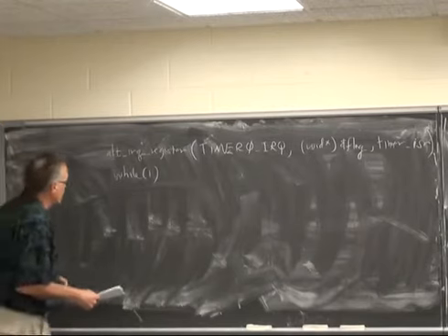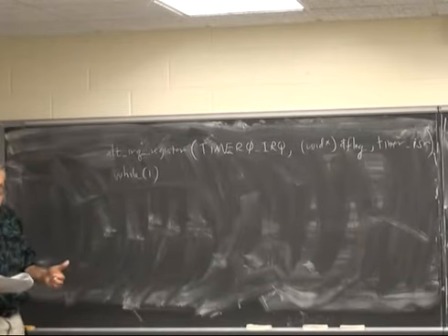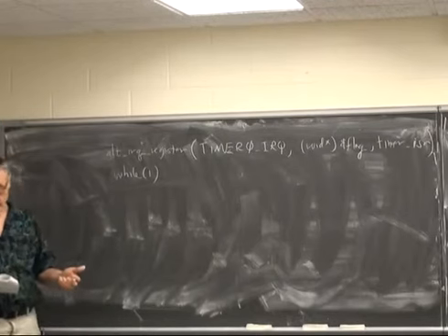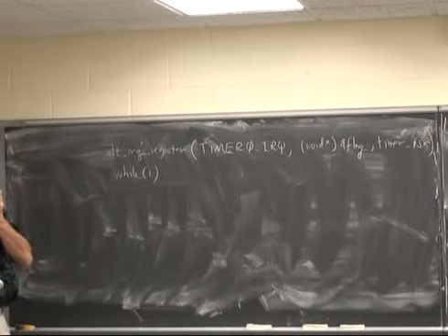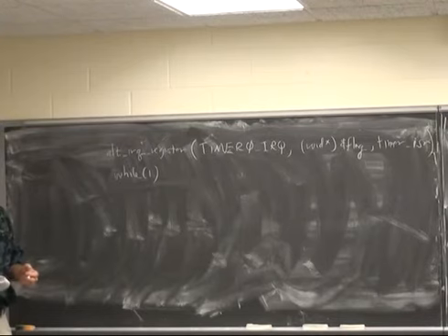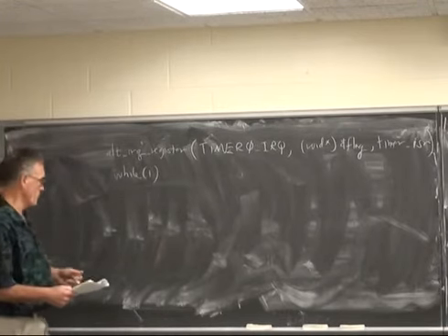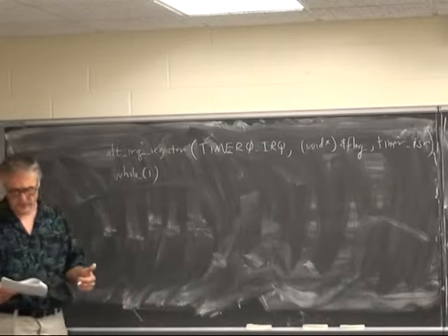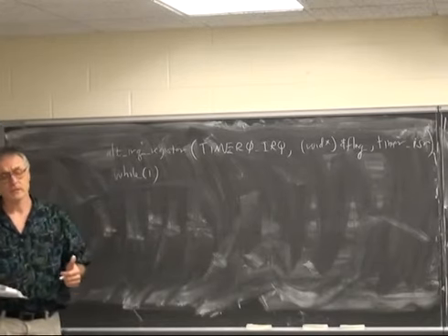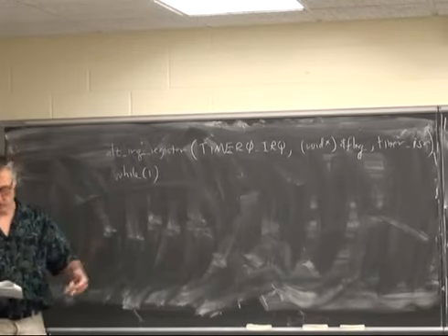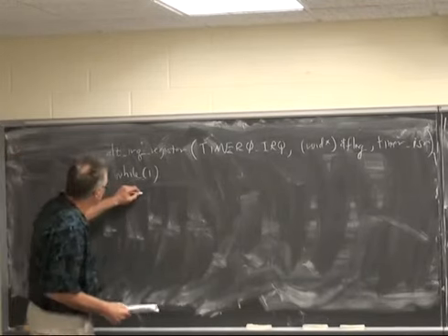What we're going to do here is read the switches, display a node index on the LEDs, output the direct digital synthesis increment, and then print the frequency of the direct digital synthesis to the LCD. So that's all it's going to be in the loop. It just goes around and around reading switches.